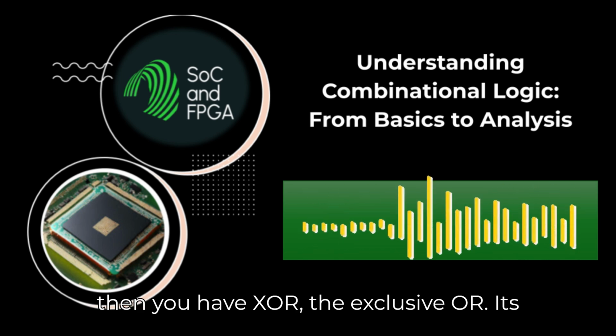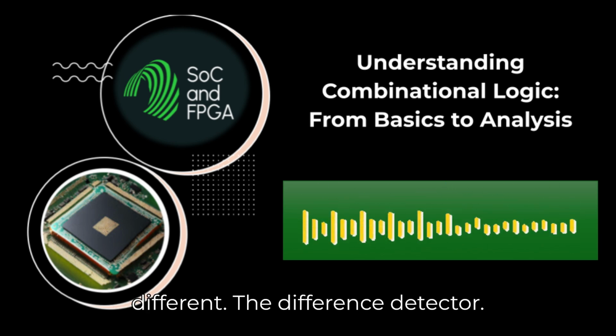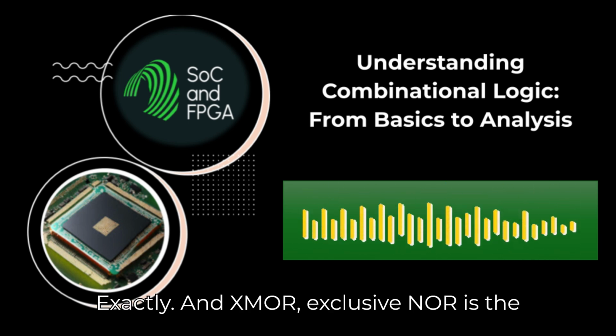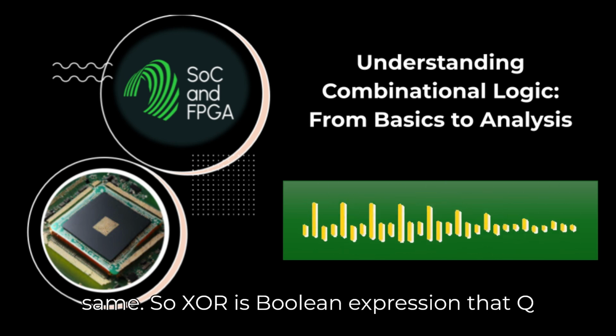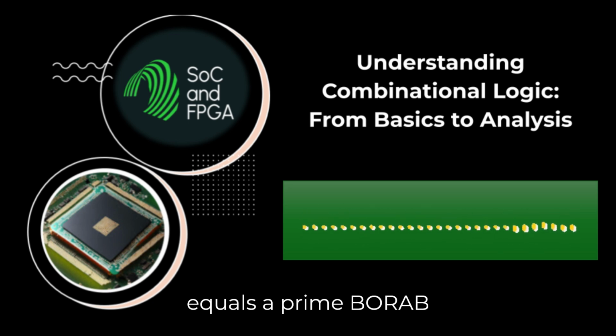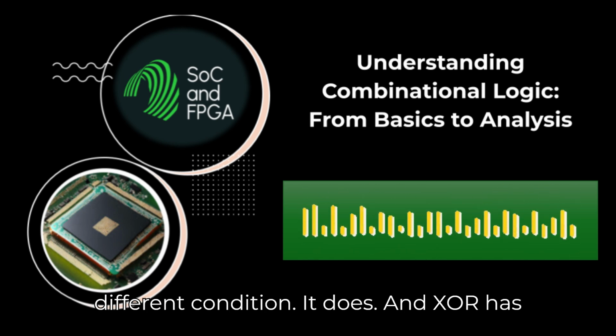And then you have XOR, the exclusive OR. Its output is high only if the inputs are different. The difference detector. Exactly. And XNOR, exclusive NOR, is the opposite: high only when inputs are the same. So XOR's Boolean expression, that Q equals A prime B OR A B prime, that really spells out the different condition. It does.